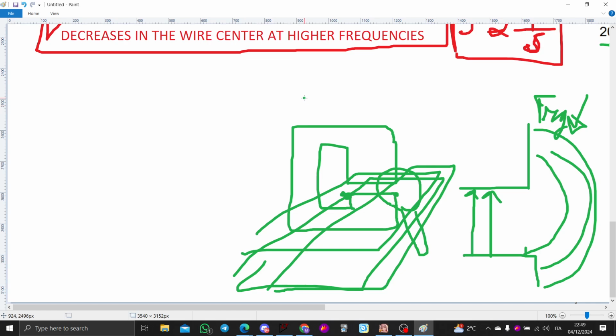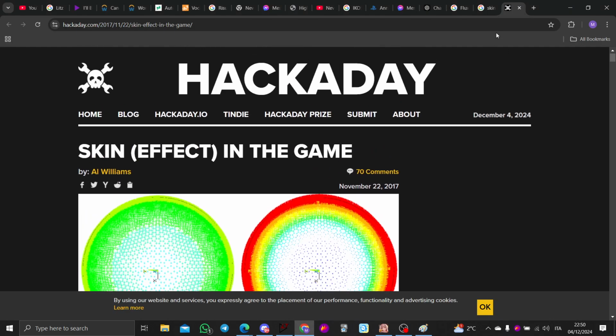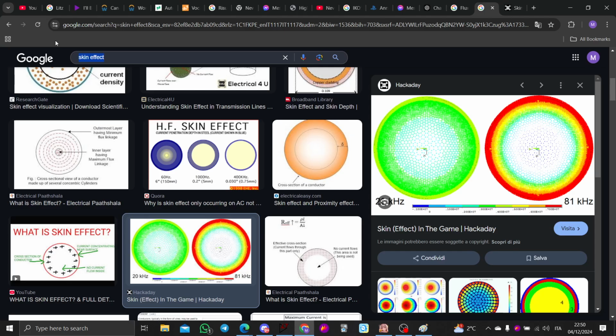If you have planar transformers, for instance, where you have the metal here, and you have all the PCB layers like this, the fringing effect on the board can latch to the layers, and this will not only create losses as well, but also EMC problems. I can type on Google again fringing effect.